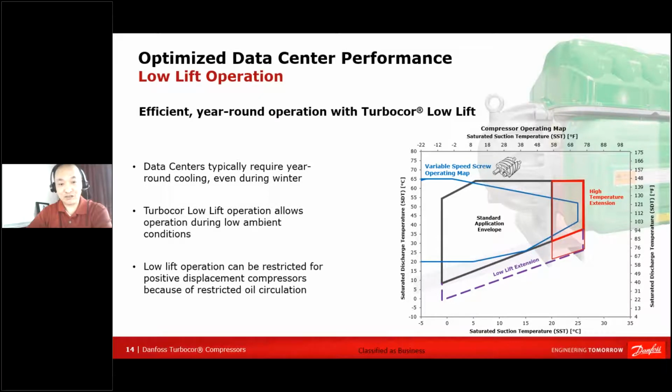Now the concern with that is that when the temperature is cold outside, the chiller that is required to cool the interior space will typically be operating in what we call a low lift condition. Low lift refers to the difference between your discharge pressure and your evaporator pressure. If your discharge pressure is fairly low, which is what it would experience at a cold ambient temperature, your lift conditions will be very small.